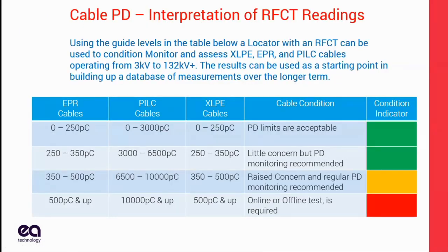These limits, we got the question yesterday about standards. There are no real international standards on what's a good and what's a bad picocoulomb rating. These are numbers that we have generated over thousands and thousands of cables that we've tested. They're much higher than you would see in a lab environment, but they're places where we see degradation. When you take these cables apart, you can see that they're getting close to failure. So this is a good rule of thumb.